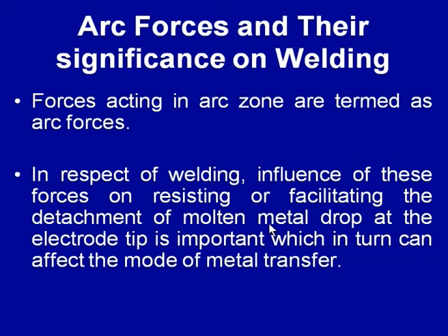For example, in case of the pinch force, which is due to the electromagnetic forces, the mode of metal transfer is affected because of the easy detachment, while the surface tension force helps to keep the molten metal drop attached to the tip of the electrode, so it resists the metal transfer.